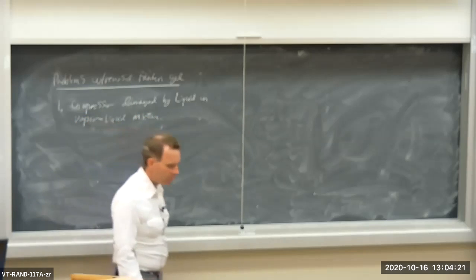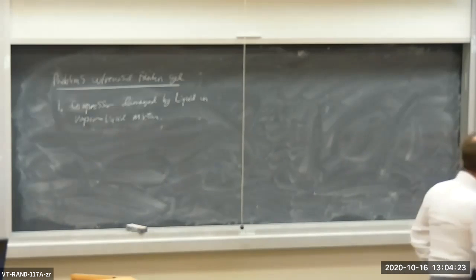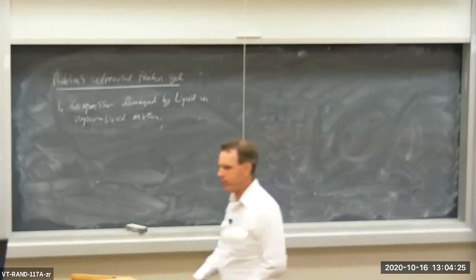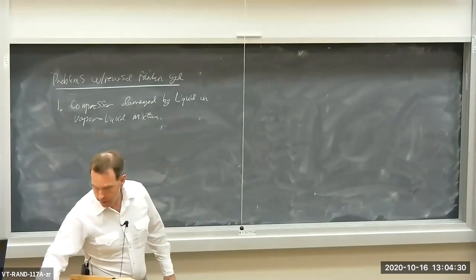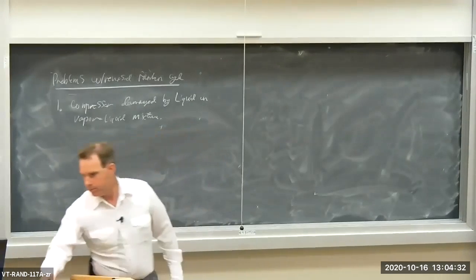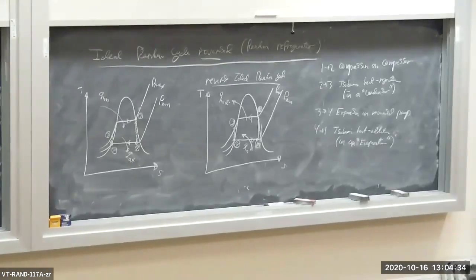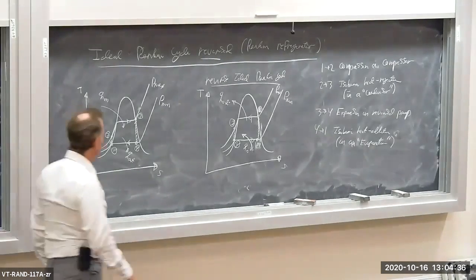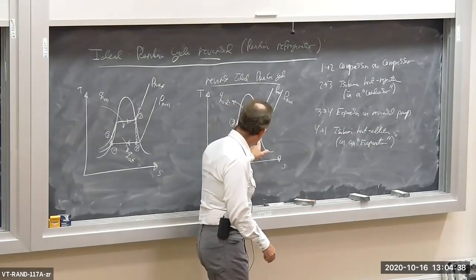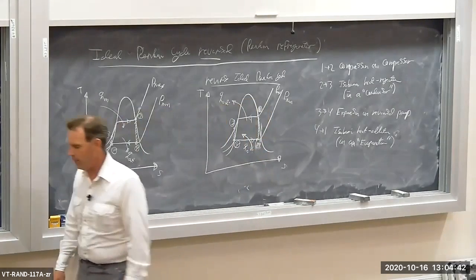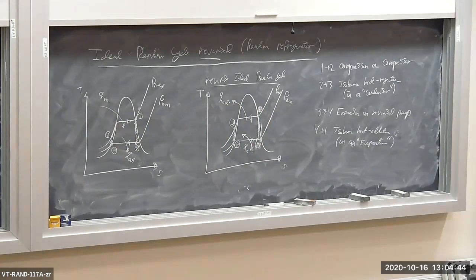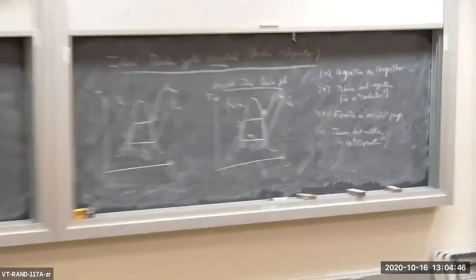Okay? If we have liquid in the intake for the compression process, we got a little bit of liquid here in the compressor intake or the beginning of the compression process. That is going to cause damage to our compressor.